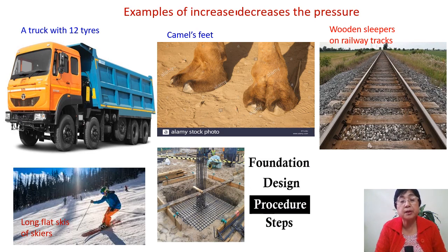a pillar with the ground broad, and this net will be attached to the standing rods. As a result, you will find this standing rod will have a broad base, resulting in more area of contact with the ground. Less pressure will be given by the pillar. So if each and every pillar is made like this, then you will have a strong foundation of the building.